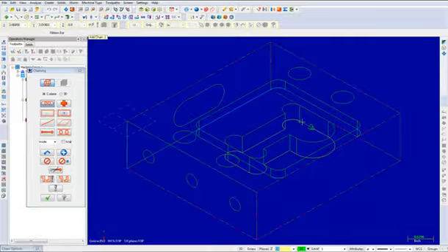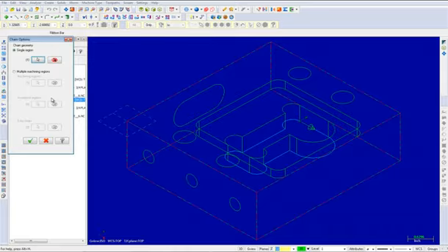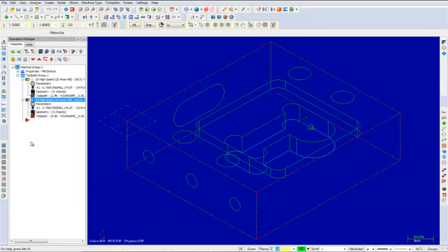Once the geometry has been selected, choose the OK button to exit the chaining dialog box. Select the OK button once again. Again, choose the OK button to exit the Chain Options dialog box. We will now select a 5/8 flat end mill from the library and set the tool parameters. Choose Parameters under operation number 2.